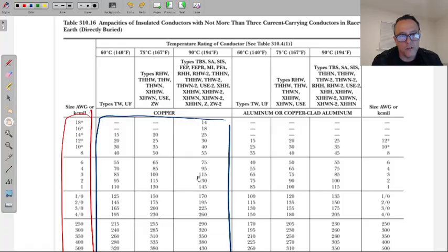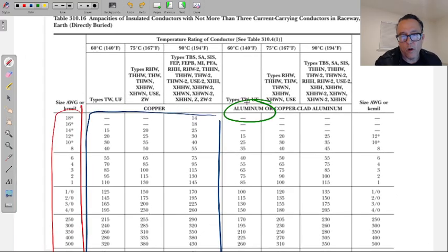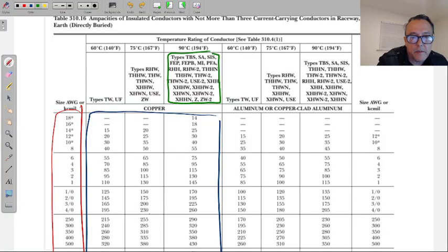All right, you have all seen a wire, I assume, and you notice there's a little bit of plastic around the wire that does not let us touch the conductor, the conductive part, whether it's copper, or aluminum, or copper clad aluminum, which is basically aluminum with a little bit of copper heated onto it. And these are a bunch of insulation types.